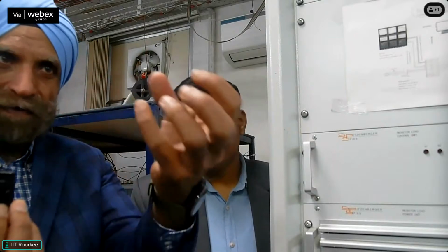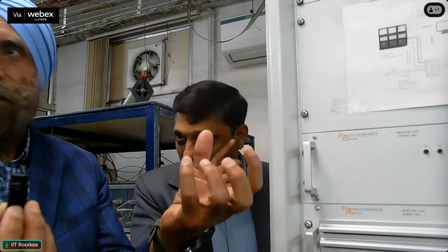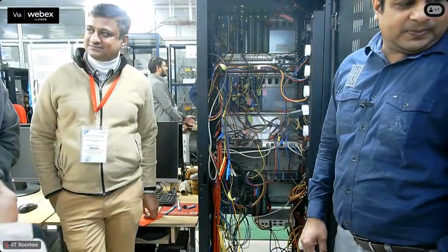So you have to give it an analog signal, and inside it, it will convert to digital signals and do the phasor calculations and so on. Whereas if you have a merging unit, you can separate that out. The role of merging units is to take analog data and just sample and give you the digital numbers. Okay, we will go to that side now.